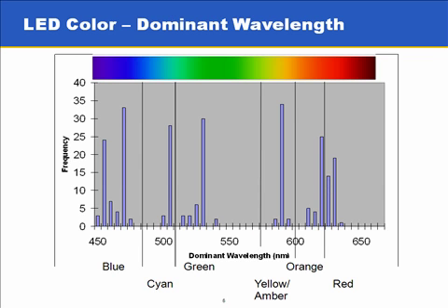This is a slide showing the different wavelengths of light coming from different LEDs in the WEBENCH tool. This is for colored LEDs, obviously, and what it is supposed to show is that one company's green is not necessarily another company's green, and particularly when you get into yellow, orange, and red, companies have different definitions of what those text values mean. So you really have to look at the dominant wavelength. And this shows you a dispersion of some of these wavelengths.